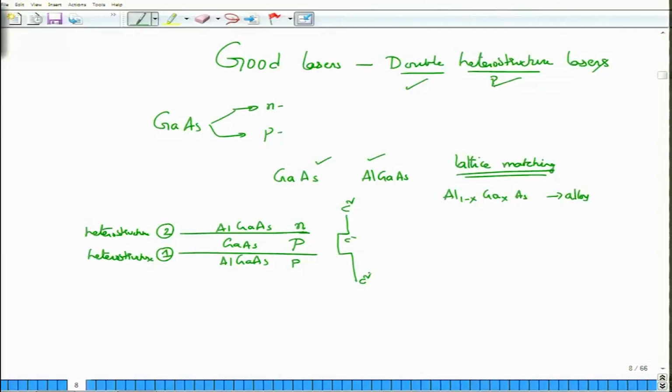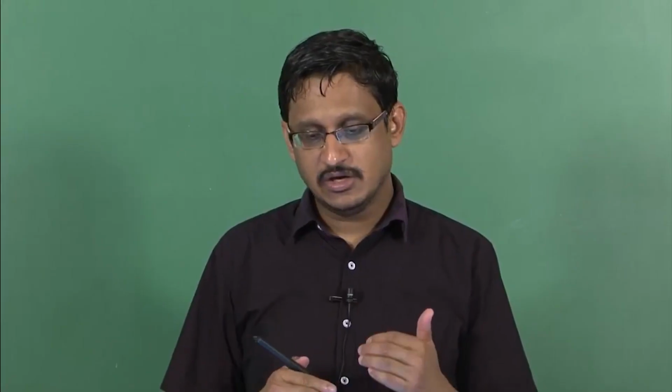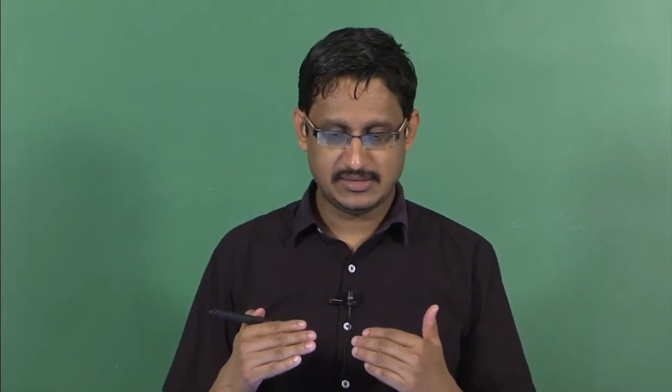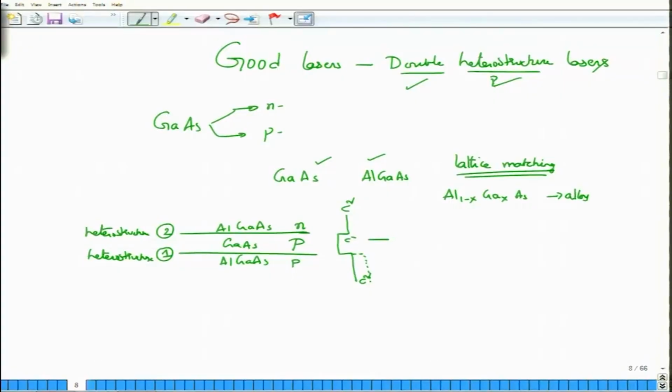Of course, I am assuming that the layers on the N and P type regions are essentially the same, so their refractive indexes are almost the same. In practice, they are not exactly the same; there is a slight mismatch because one is P doped and the other is N doped. But most importantly, even if this is not exactly the same, the central region has a larger refractive index.